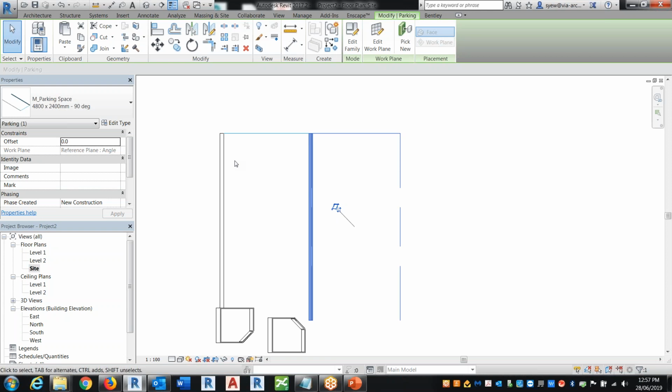So it really depends. In the early design phase, I would use the method of no work plane and not vertical. But once you get into the working drawings, the construction documentation, I always like to flip it around the other way, because I want my reference to be on the existing location where you want the dimension to go. On plan, that's more priority versus the look. So it just depends. Early design, yes, you can do this, but later on, it's completely opposite. Okay, so any questions so far?